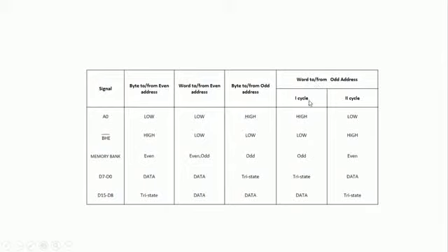During the first bus cycle, we are reading the information. The lower byte is read from where? From the upper bank, not from the lower bank. So the lower bank is disabled by applying high, the upper bank is enabled, and the information is transferred from the odd memory bank. Obviously the lower order data bus is disabled because it is in tri-state mode, and the other is carrying the valid information.